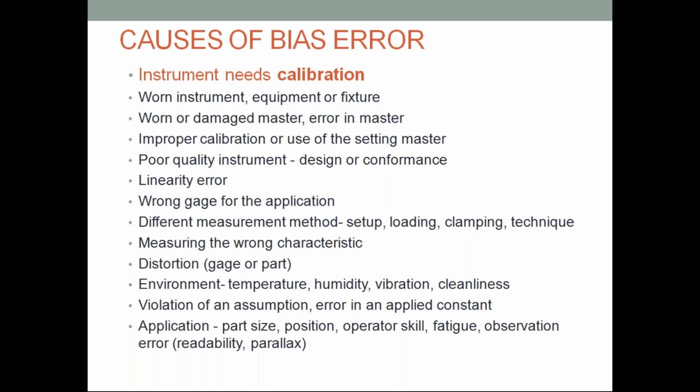There could be wear on that rule, especially on the end, that makes it inaccurate. Just because you can't make an adjustment doesn't mean you can't calibrate, ever. Adjustment is just a bonus you have for some gauges: if you're out of calibration, you don't have to throw them away, but you have the ability to adjust them and continue to use them.